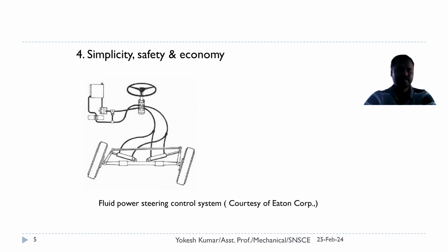Instead of this hydraulic system, if we use mechanical steering, it is very complex and a large number of mechanical elements are needed, which increases the weight and complexity of the vehicle. Moreover, from the safety point of view, if the vehicle is overloaded, mechanical failure may occur in the system, but it cannot happen in the hydraulic system. For safety, this is very suitable. From the economy point of view also, we use fewer hydraulic elements, and the cost is less than that of the mechanical system.